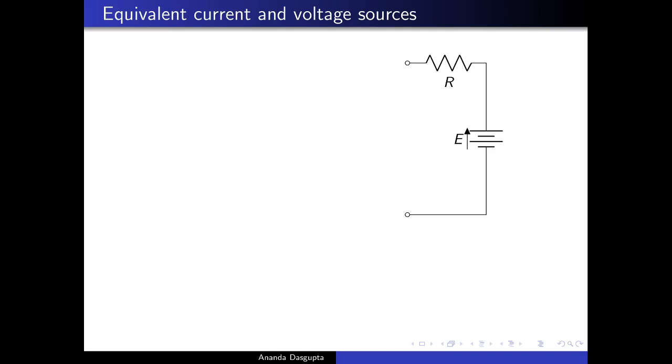How do you model this? You model this very simply by saying that a real battery is actually an ideal voltage source, an EMF source E, in series with a resistance. And what is the job of this internal resistance? Bigger the current delivered to the external world, bigger the drop across the internal resistance, so less voltage gets delivered to the external world. So this is basically it.